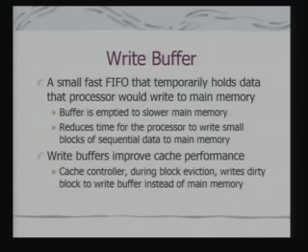A small fast FIFO that temporarily holds data that the processor would write to main memory is used many times along with cache. Now, why is this buffer used? If you remember, I talked about the basic problem of writing. When I am writing back, write back may require an overhead.